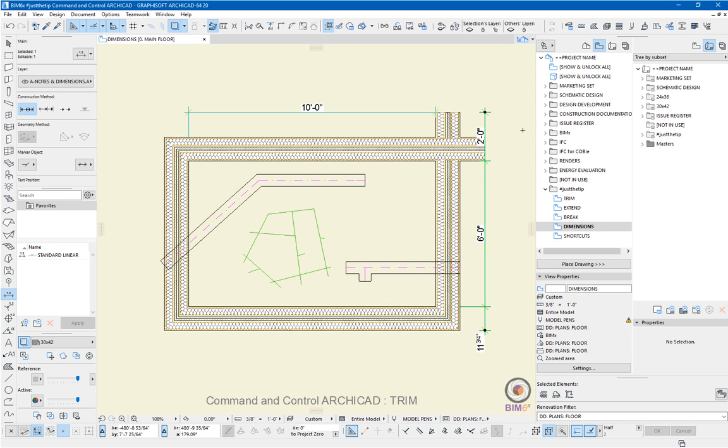additional points. If I want to add a point that's in the middle, it's a bit like break, then control click, and that adds that one. Control click in here, and that adds that one. And you can literally control click anywhere. So that's a non-associative point because it's just a random point in the middle of nowhere. So again, shortcuts, Control Z is one of these really handy universal undo shortcuts that goes across pretty much all products and all platforms. Can select this dimension line, and we can just add in key points with a simple control click, and it's nice and simple and easy to do.